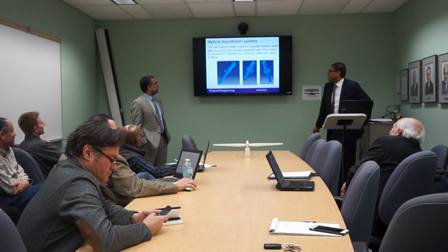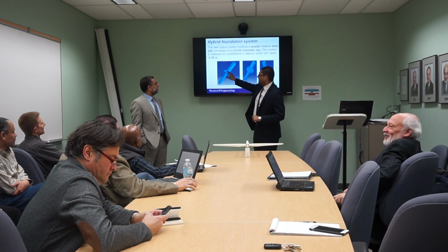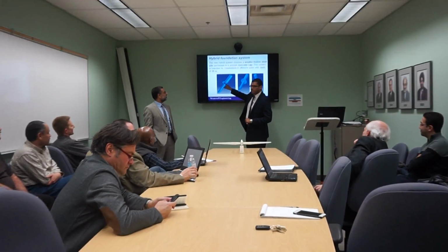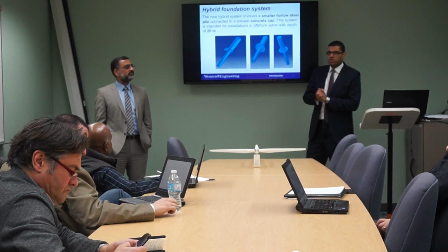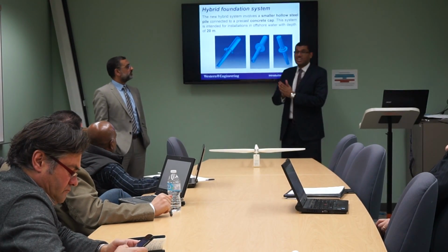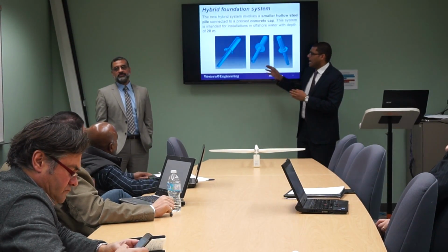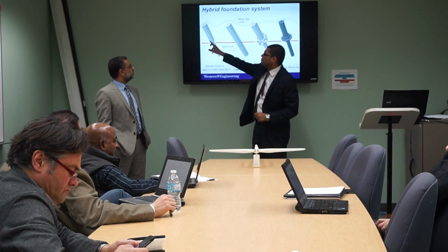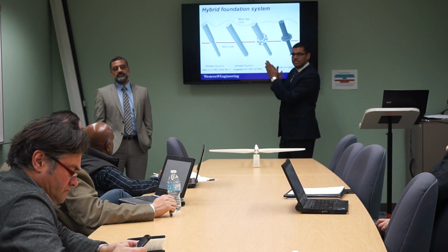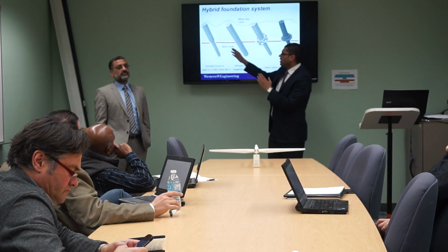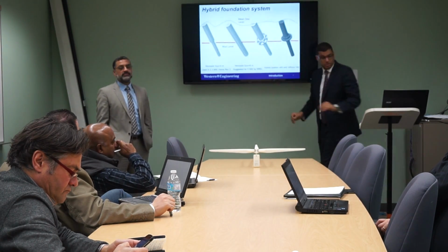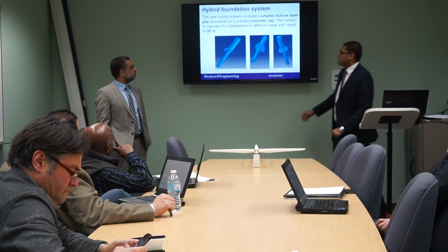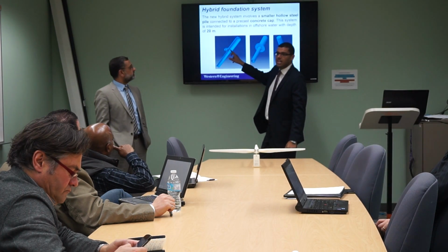Okay, so here's the little thing. Usually in the connection here, the DNV code makes all the specifications for a grouted connection, because it assumes, as I said, in this system that there will be little distance between the two parts. So all its specifications are just for the grout. But in our case here, we have at least 1 meter diameter thickness.